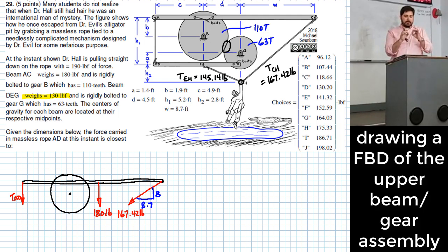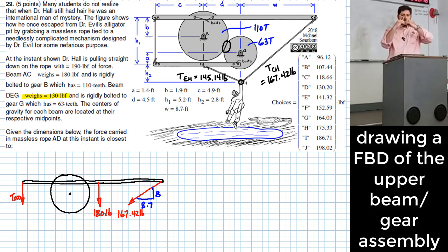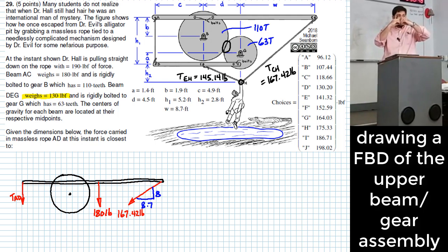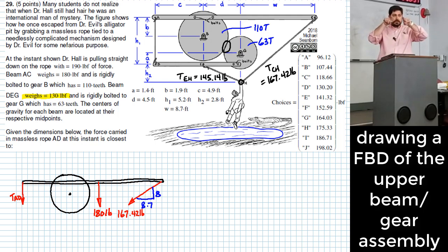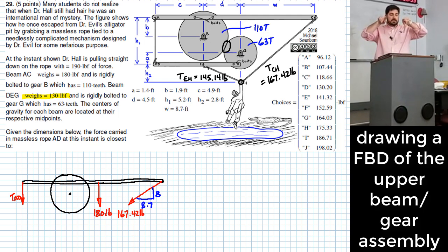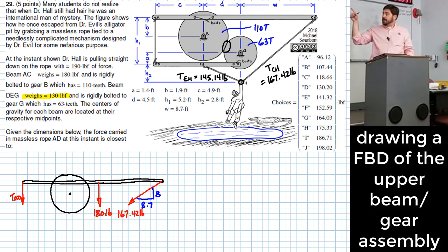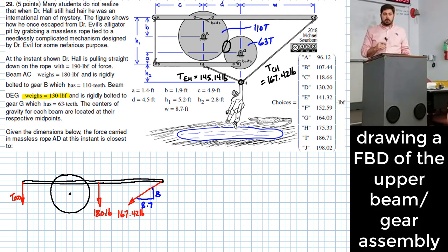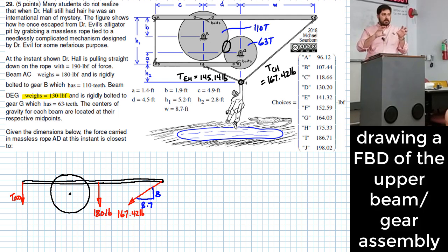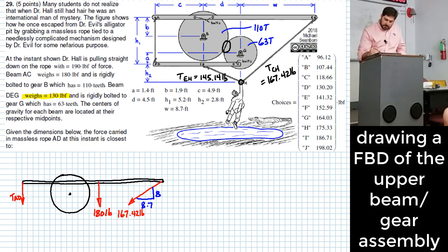Since gears basically turn in opposite directions, if you apply torque in opposite directions, it would tend to make them accelerate because nothing would cause them to slow down. So really, when we have two gears interacting like this, we want to assume torque in the same direction, because that's ultimately the way the two would interact with each other. So I'm going to also show a counterclockwise torque on here.